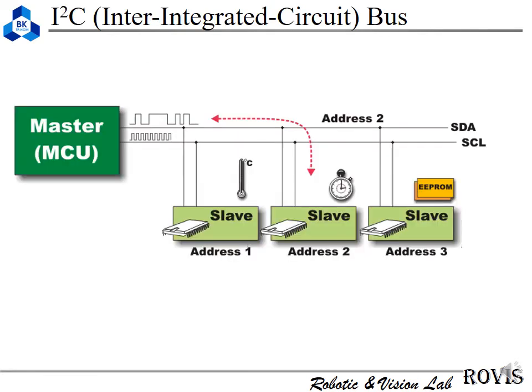And what is the function of the I2C? In this slide, for example, we have an MCU, which we call the master, and we have multiple slaves. From one master we can transmit the data to many slaves, using just two lines, SDA and SCL.